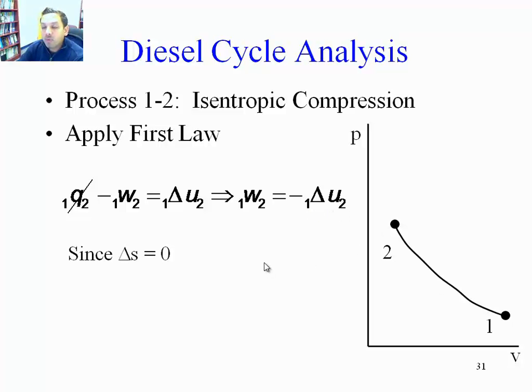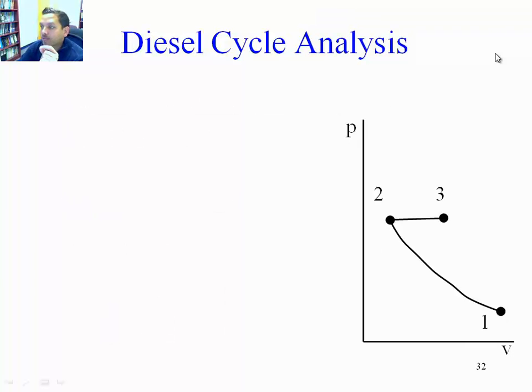Same thing we did before. Now the volume is moving from bottom dead center to top dead center through the compression ratio, which is usually higher in diesel engines. Because this process is isentropic, we can relate the volumes from 1 to 2 to the VRs from 1 to 2, which are functions of temperature, through the compression ratio. Same thing we did for the Otto cycle.